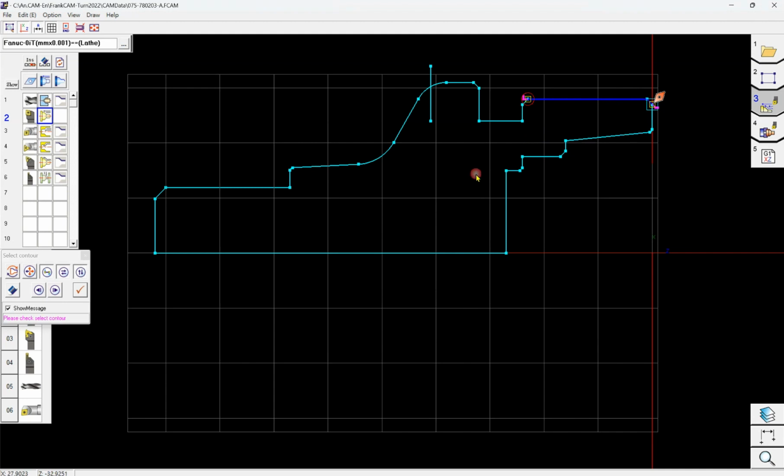When the contour changes up and down, a message pops up to ask you which way you are going. If you want to skip the groove, you click the line here. It will connect the contour directly and keep selecting the contour according to your pictures automatically. You can adjust your endpoint a little bit backward and press OK to confirm.